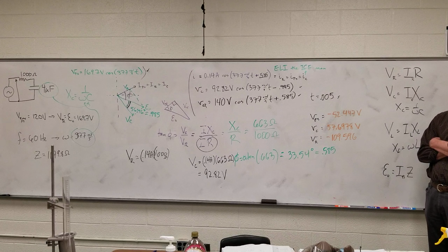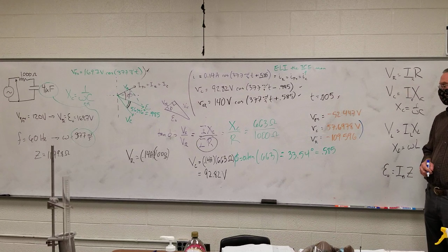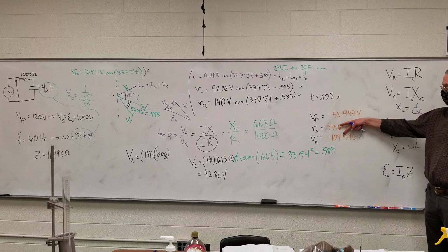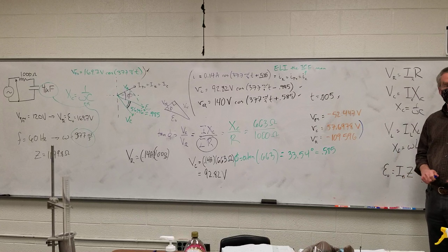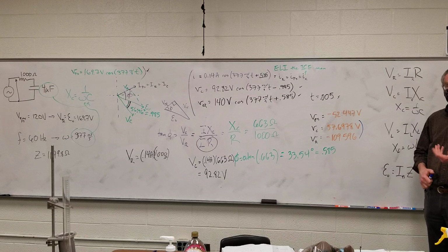I did the voltage of the power supply should equal the sum of the other two voltages. Yep. And it looks like it's pretty darn close. At a crude level, this would be negative 52 if you add them together. We got negative 52 there. Yeah. It's off by like half a volt, I think. And considering the order of magnitude, I'm okay with the 1% off.